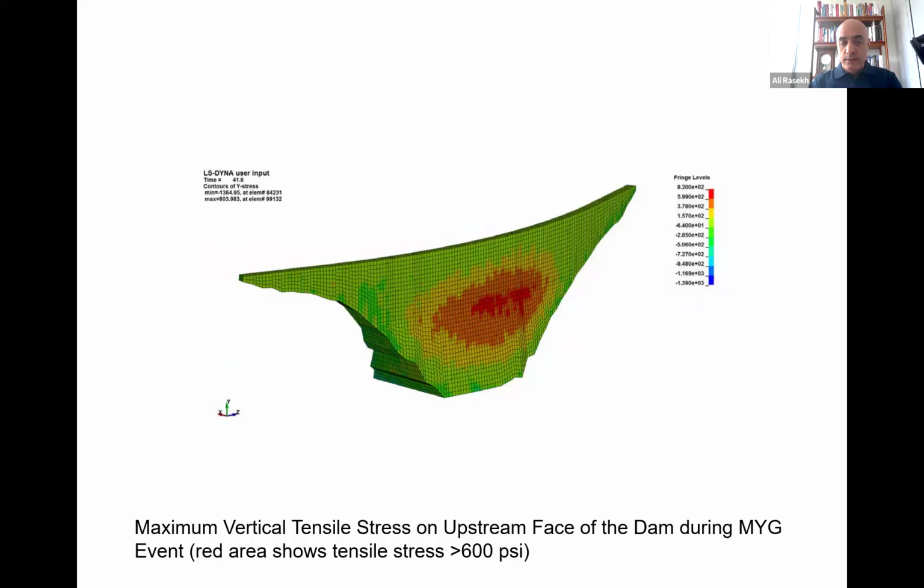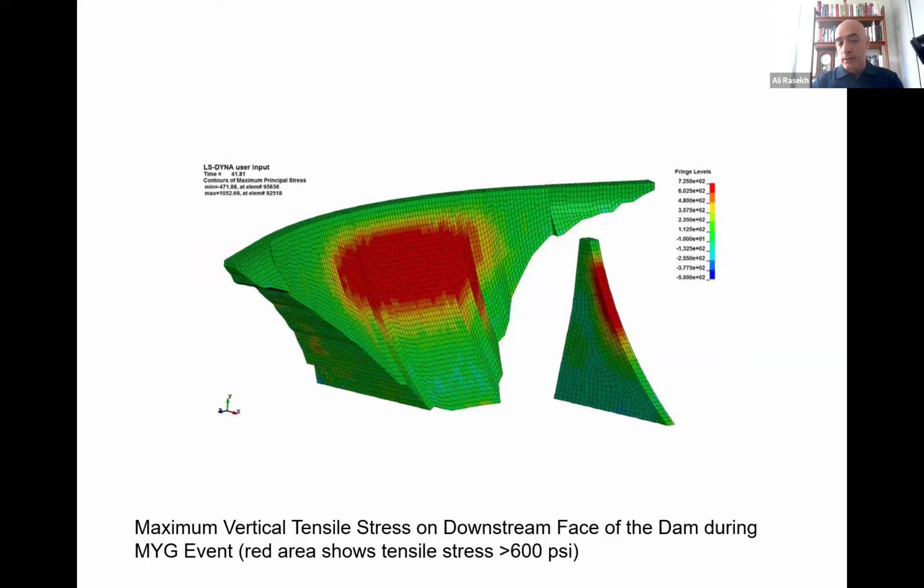Again, it's always stresses. Dams, obviously, are not reinforced. Maybe in some cases there is some superficial reinforcement, but putting reinforcement in these huge structures normally wouldn't be economical. So there should be a really strong reason to put in reinforcement. In this case, stresses are more important.